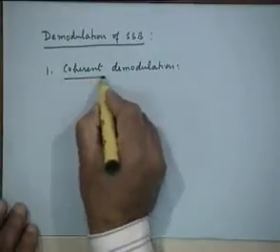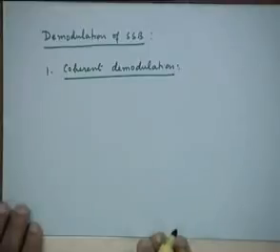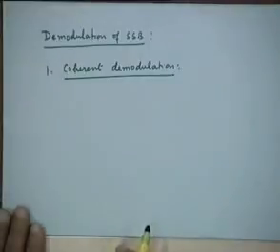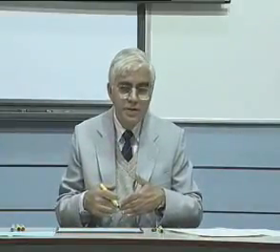Let's consider what will happen in this case when it is not coherent. Remember we carried out this discussion for the case of the DSB-SC signal, and we understood that due to a phase offset the signal will be attenuated, right, and due to a frequency offset we will see the so-called wobbling effect.